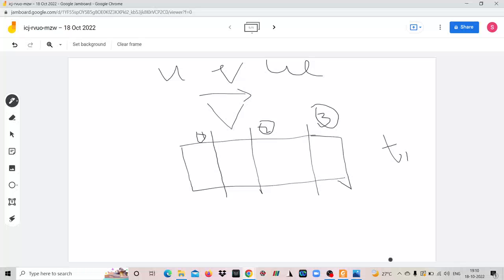Yeah, it is only with respect to space and only the velocity component. Clear? But it may change with time, sir. Yeah, it may change with time. Means if it changes with time, then it will be unsteady uniform. If it does not change with time, then it will be steady uniform. Okay, so along the direction of the flow, it should not change. Yeah. Velocity should not change along spatial coordinates.